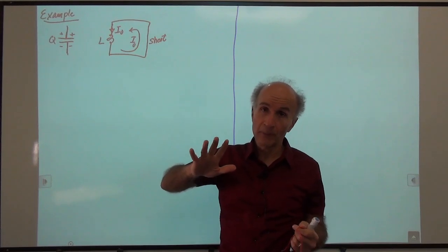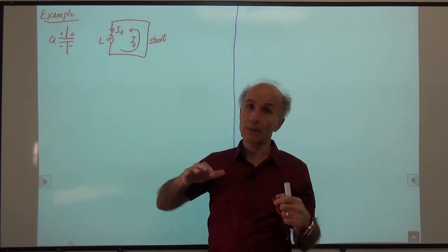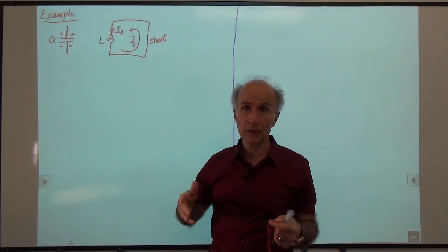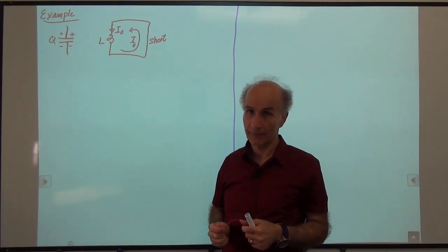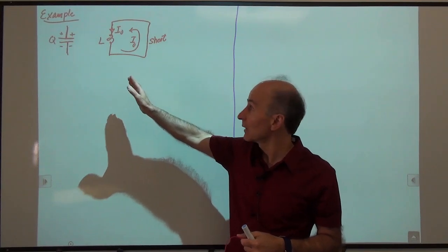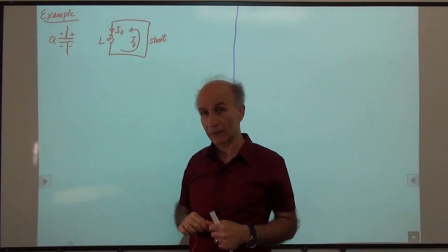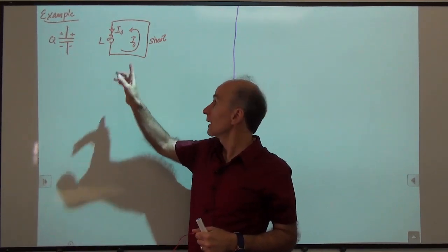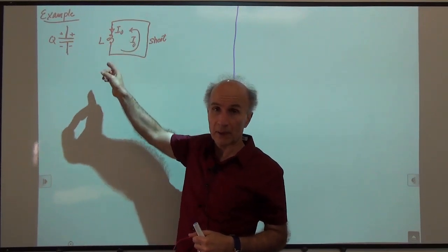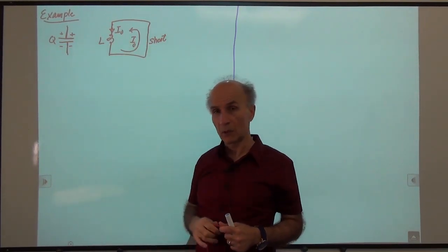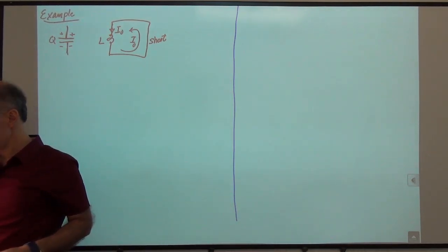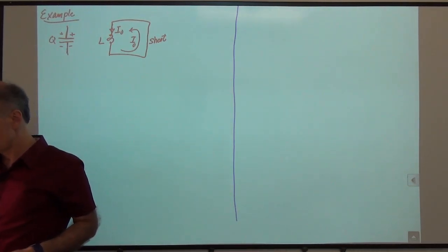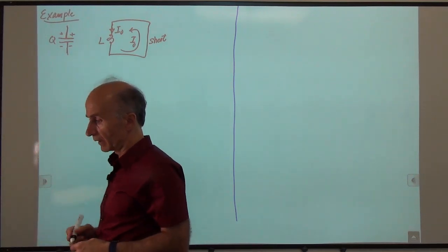But in principle, if we want to keep the current through an inductor forever, we have to short the inductor between its terminals. This is the dual situation of what we have for a capacitor. So we create a circulating circuit, and the current circulates around this loop. That's good to remember because we will see that the situation becomes more interesting as we go along.